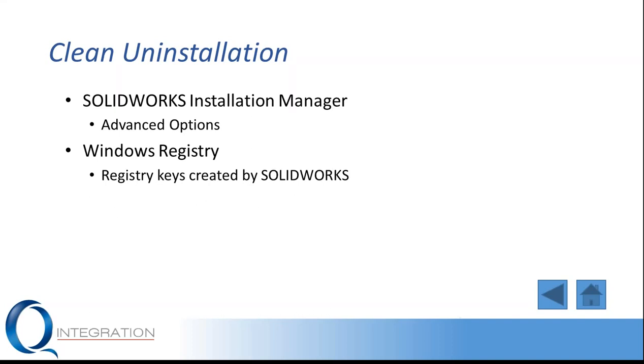And if you choose change, you have the ability to get in there and either delete the registry items, delete folders, delete the downloaded location for SolidWorks install files. And it gives you a list of everything that is actually being deleted. Now, I highly recommend that as you click on these different advanced options for the uninstall, that you're verifying what is actually being uninstalled there, what it is adding for locations.